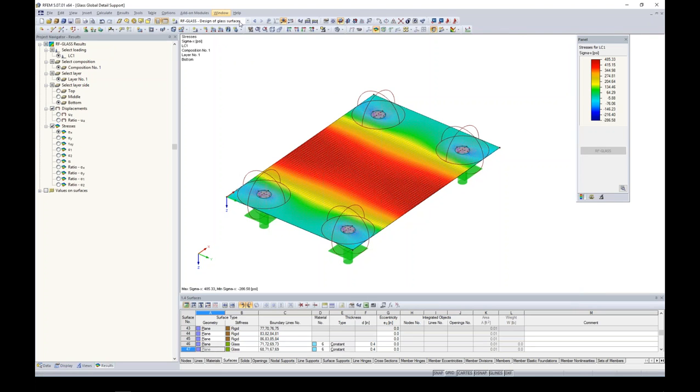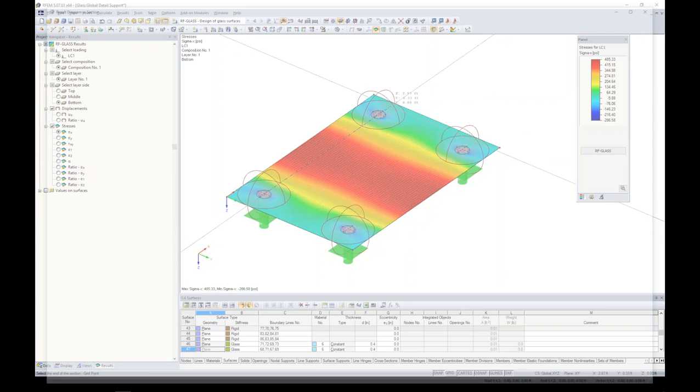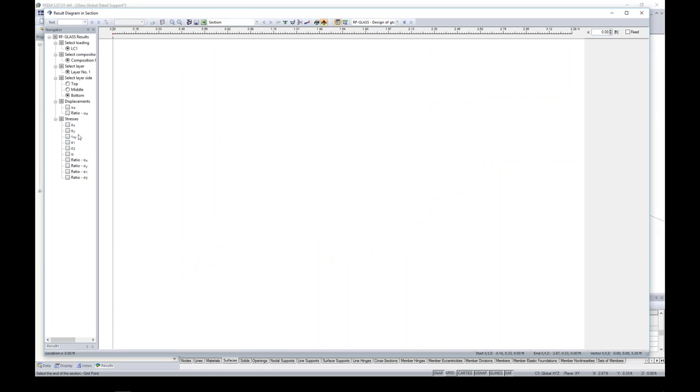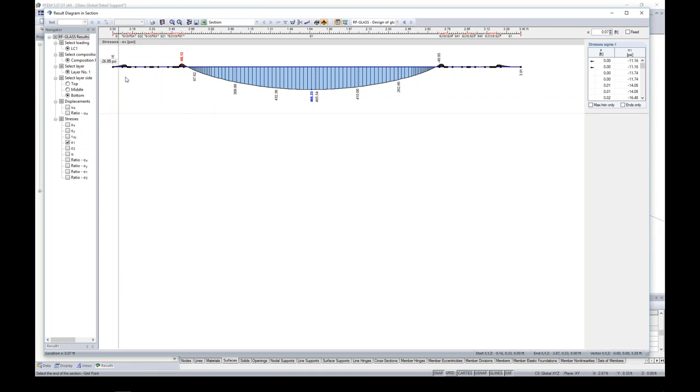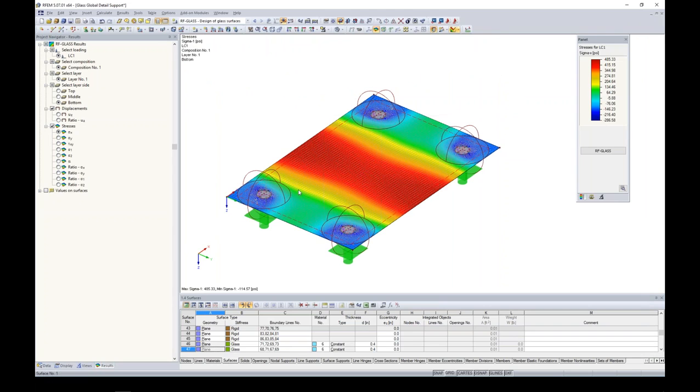Sorry about that. Okay, so choosing one of these section cuts, maybe I want a little bit more detail through these supports here because the contours are nice, but we don't really get any numerical results. Well, here we can go ahead and turn on, let's say, one of our normal forces, sigma 1, and you can turn on any of the stresses that you like. Here you can view it across that surface where we just made our cut for numbers instead of just purely contours.